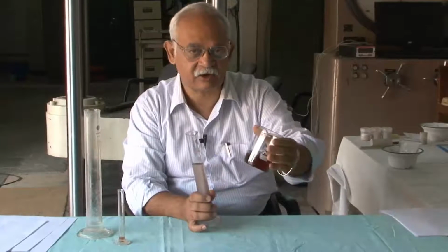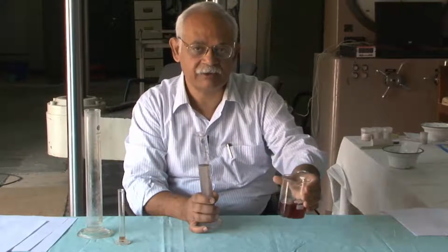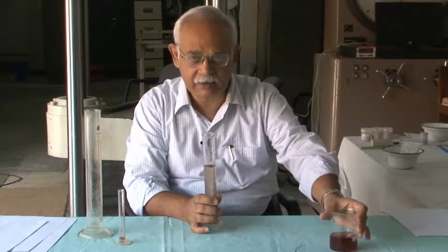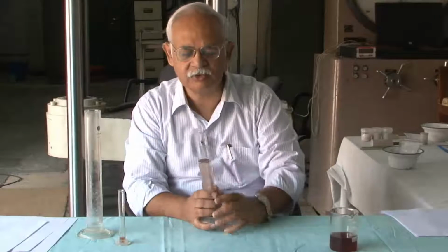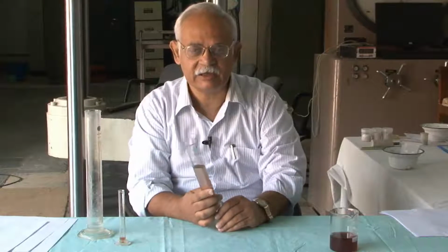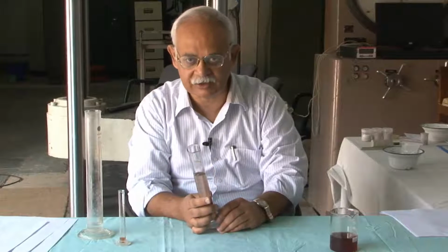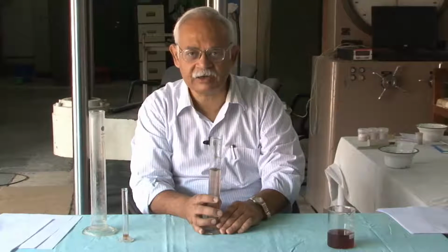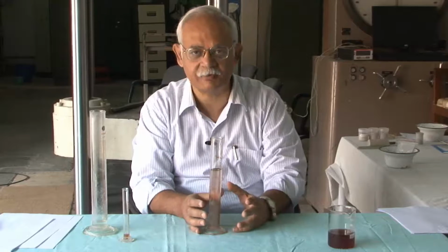So, we rarely use chemical admixtures in their concentrated form, but we use them in a diluted form. We do an appropriate dilution and use the diluted chemical admixture as part of the mixing water. This ensures a better distribution throughout the concrete mass.